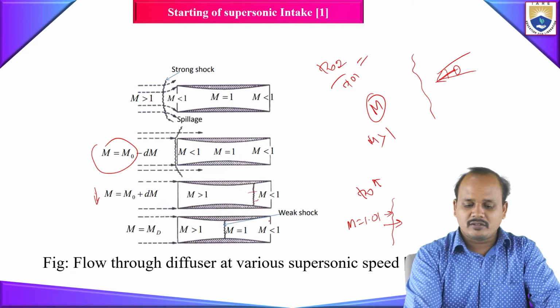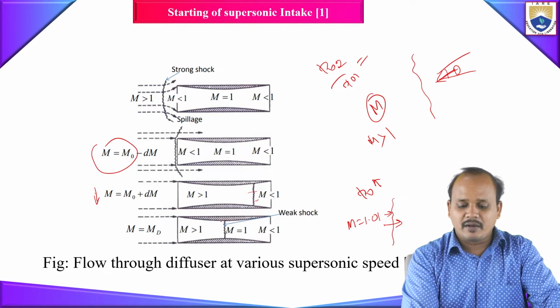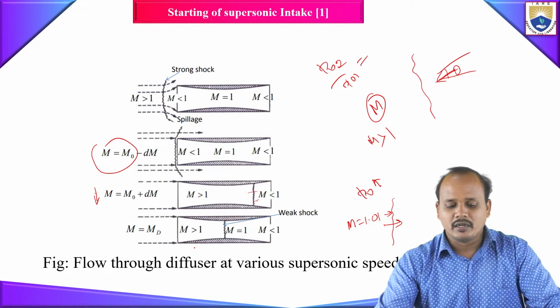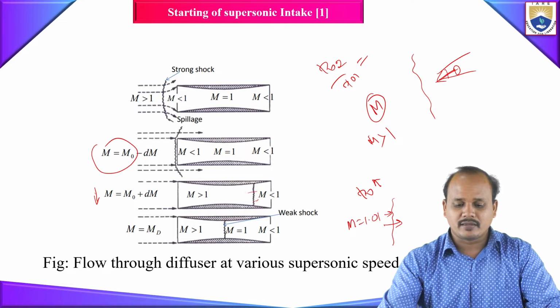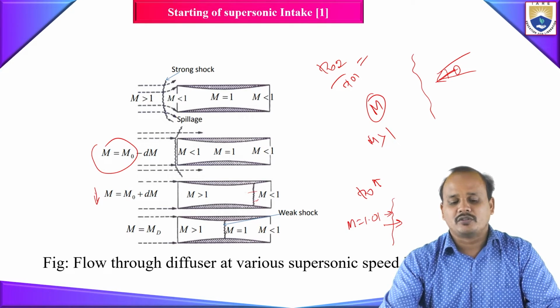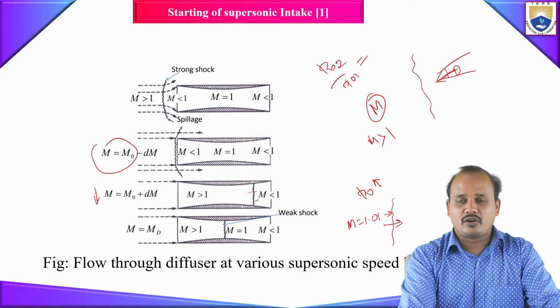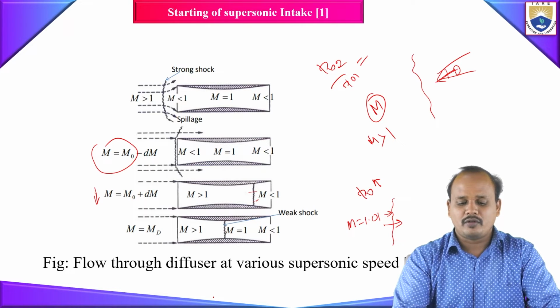Okay, this process of how we establish this standing normal shock wave slightly downstream of your throat location, we call it the starting of your supersonic intake. Okay, so it has to go through multiple processes if you want to situate your shock wave slightly downstream of your throat location.